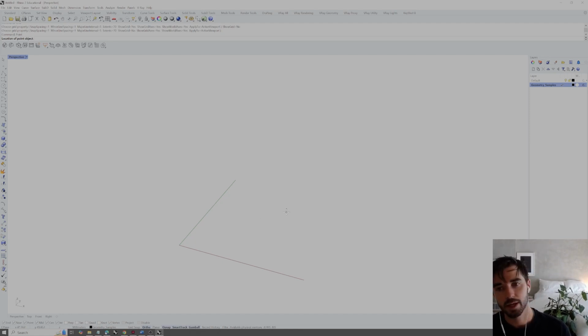That C-plane by default is the XY plane, so it will instantiate a point somewhere on the y-axis, somewhere on the x-axis, but we know it's actually going to be at the 0 point in the z coordinate plane. So if I click here, we have 1 point object added.